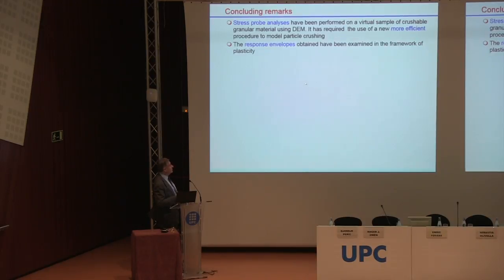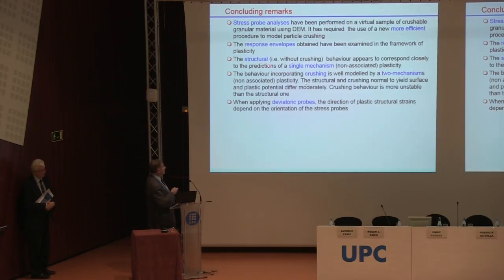So let me conclude that we have carried out a stress probe analysis, which has been performed on a virtual sample of crushable granular material using DEM, and it's been essential to apply this new procedure, which allows a much more efficient modeling of these events, and quite realistic too. We have seen that the structural plastic strains without crushing appear to correspond very closely to the predictions of a single mechanism of non-associated plasticity. This perhaps explains why these sorts of models are so popular in geotechnics and soil mechanics.